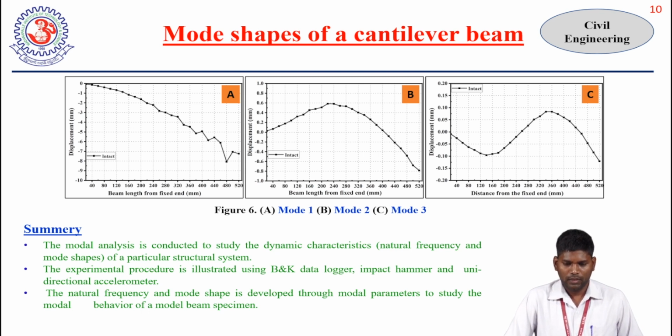In summary, I can say modal analysis is conducted to study the dynamic characteristics, that is, natural frequency and mode shapes. Here only two parameters have been taken to analyze the structures. If there is any variation in the structure or any damage occurring in the structure, this mode shape and natural frequency are going to change.